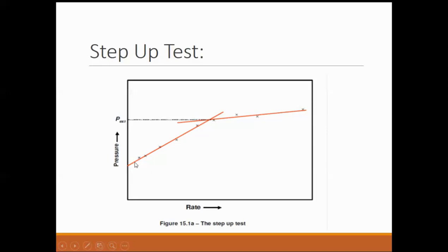So this is the kind of output that these softwares produce. They basically give you the stress profiles and the kind of width that you have created in the formation. This is basically a 3D model, because there is width, height and length. Different colors show different widths, that is, at what point in the fracture, what kind of width you have created. So this is a 3D modeling of that.